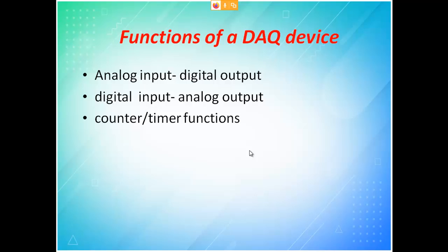The function of DAQ is analog input to digital output, digital input to analog output, and counter and timer functions. You might have come across something called counters and timers. In detail we will see what counters and timers are when you come to embedded systems. A counter is going to count from a value you have loaded till the value you have also loaded to reach.